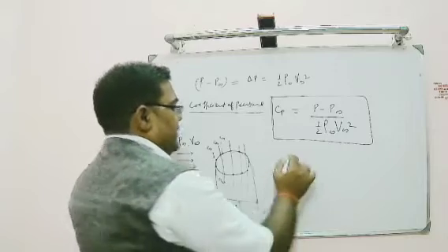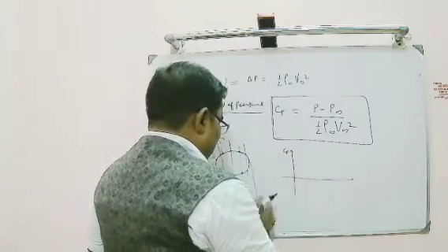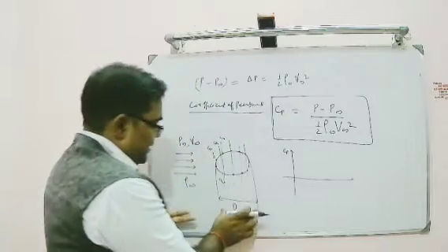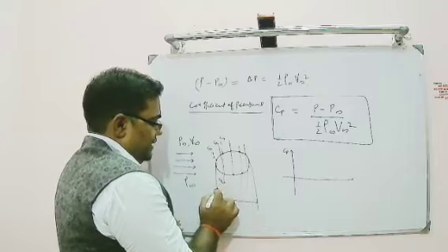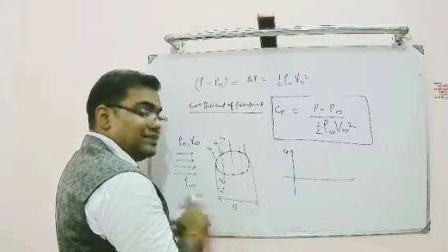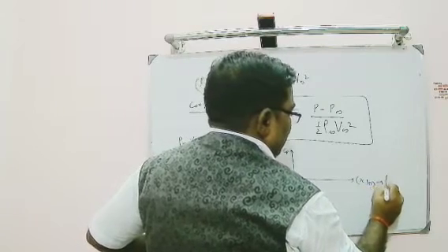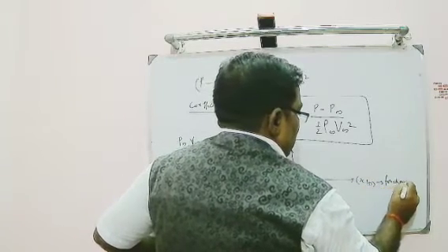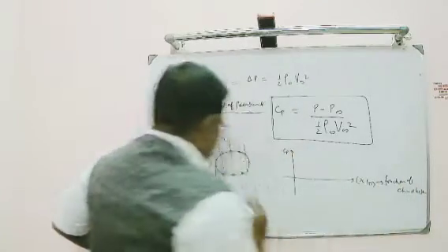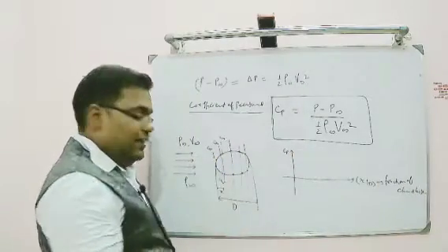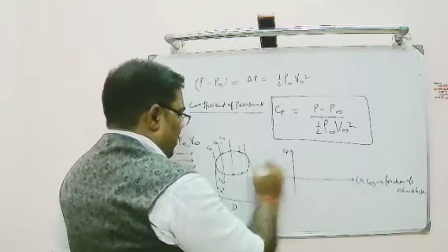Finally, if you draw it, here Cp, and here the fraction of this diameter. What is the length of the fraction I am saying? This x, any distance along this. So I say x divided by d, this is known as the fraction of chord length. If I am assuming this circular cylinder as my airfoil, this is the chord length, so some distance of this, so I can now plot these points.